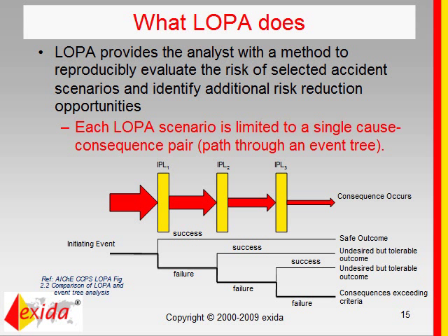How can you look at this? Well, let's say the big arrow on the left is the initiating event with a certain level of risk. We have protection layers, and those protection layers reduce the risk. So we have protection layer 1, protection layer 2, protection layer 3, and we end up with an event frequency that is much lower with a lower level of risk associated with it. So these three protection layers basically reduce that initial big arrow to the smaller, narrower arrow.